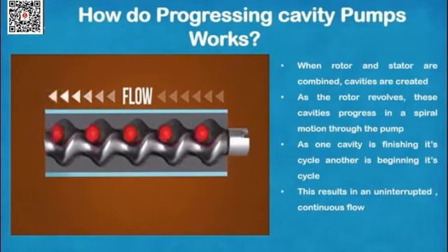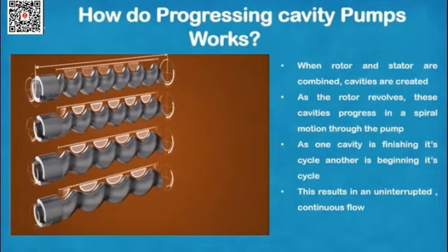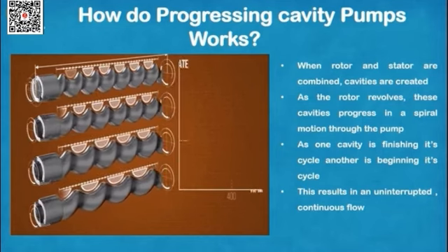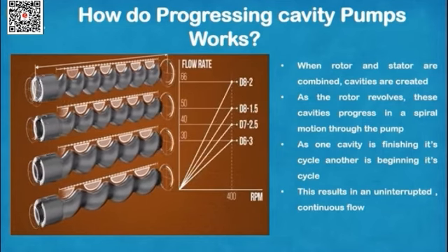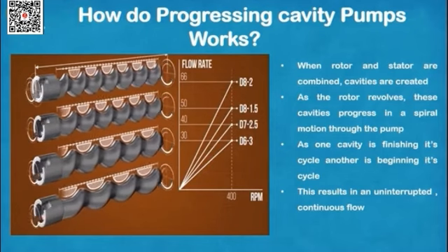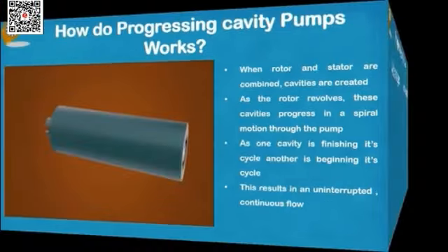An important consideration with progressive cavity pump stators is the geometry profile. Generally, there are 4 different stator geometry technologies in the marketplace. Different flow rate and pressure stability are achieved by varying the design, so choose the right stator, depending on the features of the fluid.